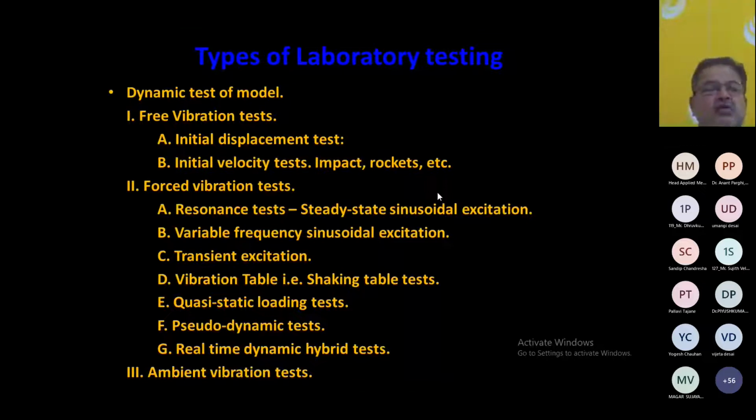Then your structure is going to exhibit a large response, right? So that is on the resonance. So we perform resonance test. Variable frequency sinusoidal excitation. So basically we are applying the external excitation force in form of a sine curve, right?